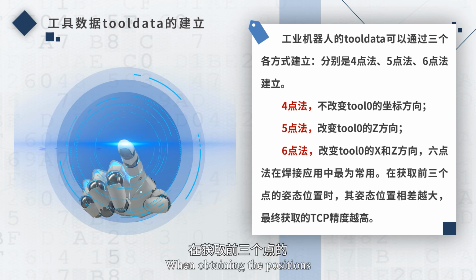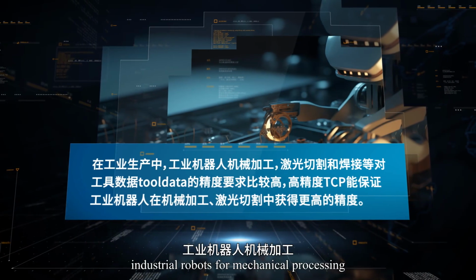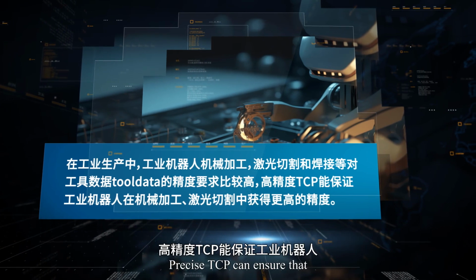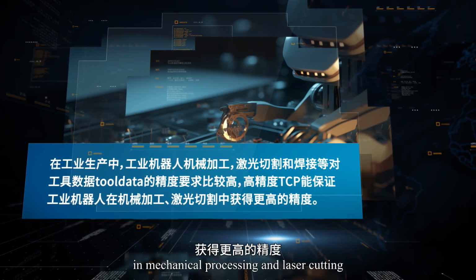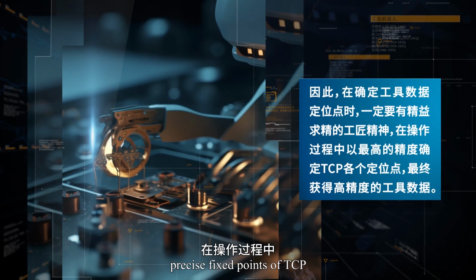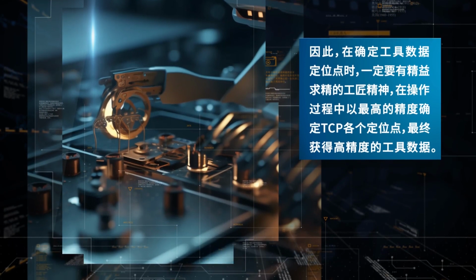When obtaining the positions of the first 3 points, the greater the distance between their positions, the higher the accuracy. In industrial production, industrial robots for mechanical processing, laser cutting, and welding require high accuracy of tool data. Precise TCP can ensure that industrial robots achieve higher accuracy in mechanical processing and laser cutting. Therefore, when determining fixed points, it is necessary to make sure precise fixed points of TCP in order to obtain precise tool data in the operation.